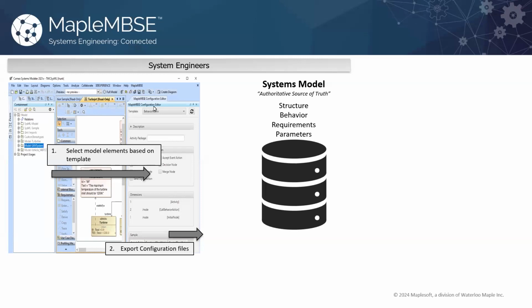You just need to select the plugin template that you want to work with. By a template, I mean you would be able to generate views for the subject matter experts. So these views would be, for example, say you want to create a hierarchy of the system model, or you want to maintain certain traceability for the system model, or you want to define a behavioral aspect for the system model, and so on. So you select a template based on a use case that you want to work. You drag and drop the information from the model containment tree. So it is as simple as that.